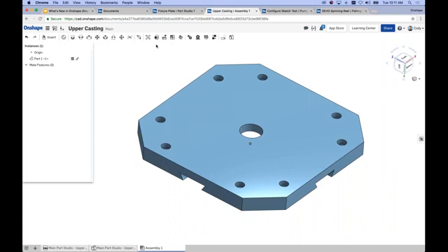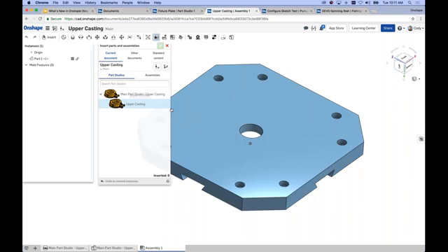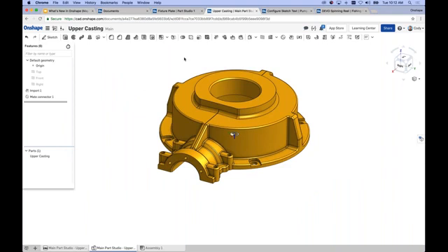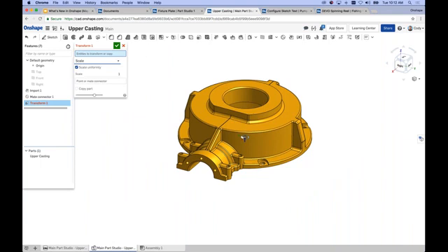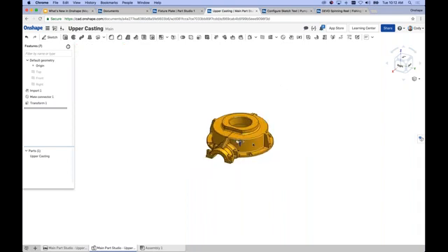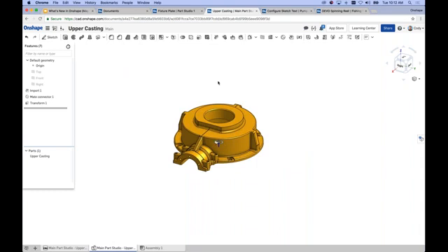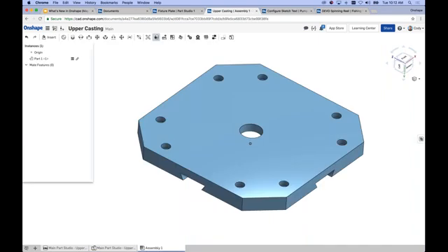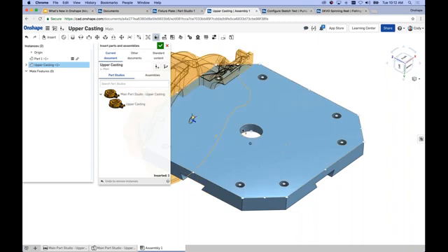To make this faster, let's turn on snap mode and use that mate connector. Insert, upper casting. Oh, one step that I forgot, forgive me. Let's scale this because at first it is way too big. 2.375. And we'll use that. There we go. So it'll actually match the part we're attaching it to. So now I want to insert into this, right?